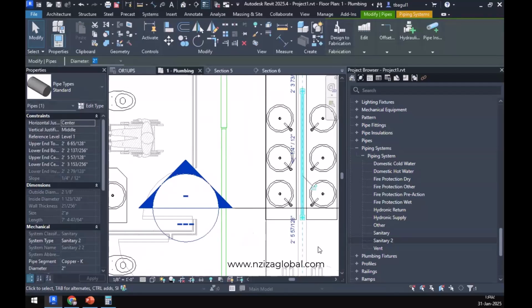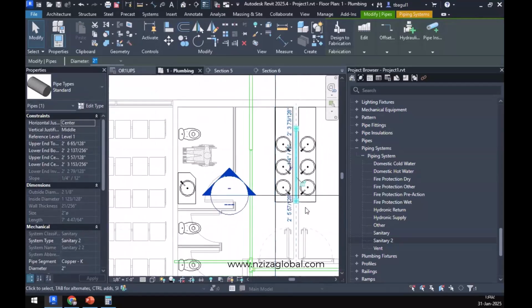You can have it on the surface of the wall, but push the architect to have some kind of casework below this particular plumbing fixtures. Yes, some kind of casework below it so that people will not bump into that plumbing fixtures, or it will not be readily accessible to the pipes, or not plumbing fixture, to the pipes. It is fine, right? Just make sure you coordinate that with the architect. And the best case for us is to have a small chase that can have all the pipes go through it. Best case, all right? But best case seldom happens. I'm aware of that, all right?